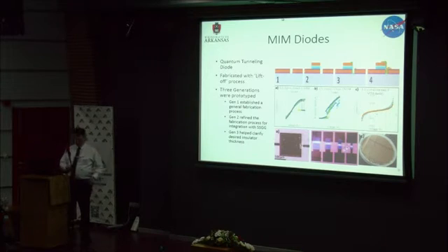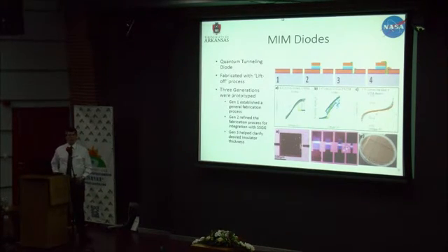This is the diodes. The MIM diode is a metal-insulator-metal diode. It's a quantum tunneling diode. It's not a semiconductor diode. It has an insulating membrane between two metals that experiences quantum tunneling breakdown above a certain applied voltage.